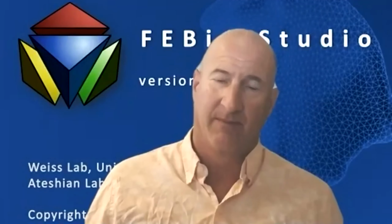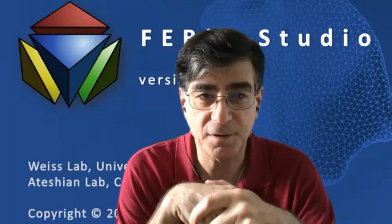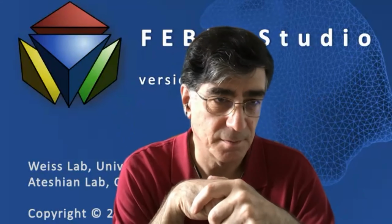Gerard, you're saying you've tried to create those elements and didn't? No, so I just used the default 3-field formulation. So for hex 20 elements, it would only have one J value. It wouldn't be like a linear interpolation of the determinant of the deformation. Yeah, so in summary, we have this 3-field formulation only, I believe, implemented for the hex 8 elements.